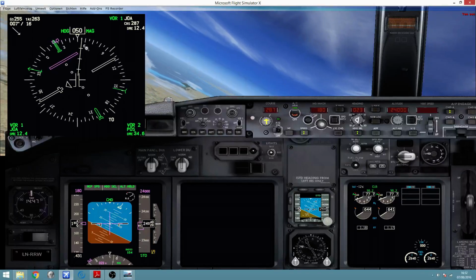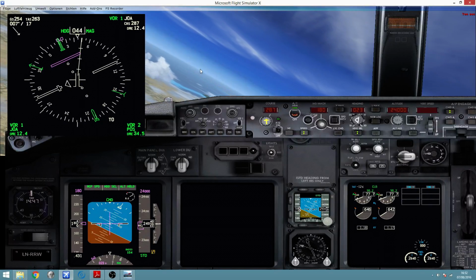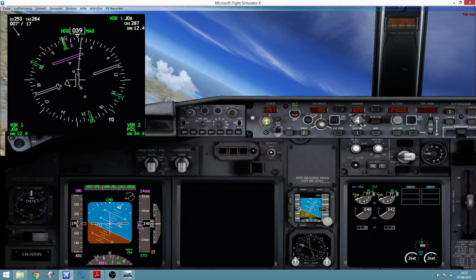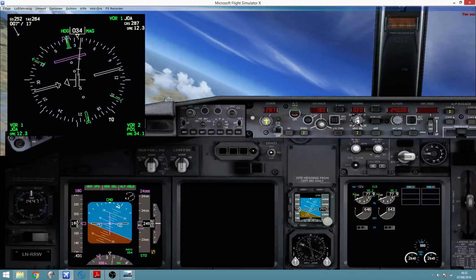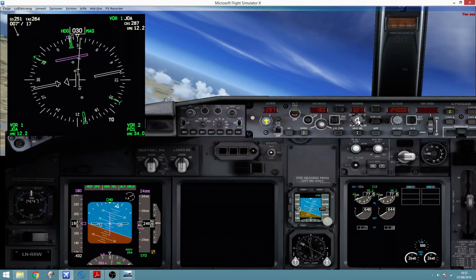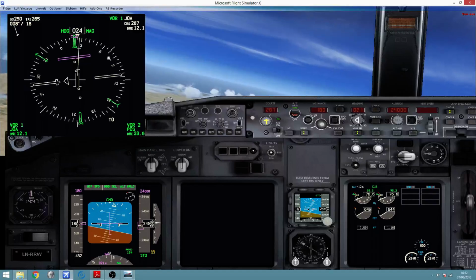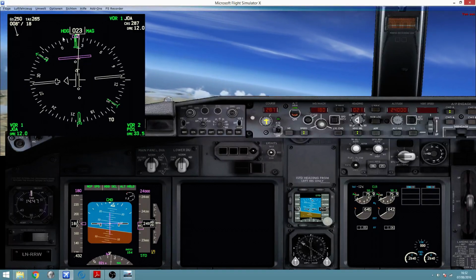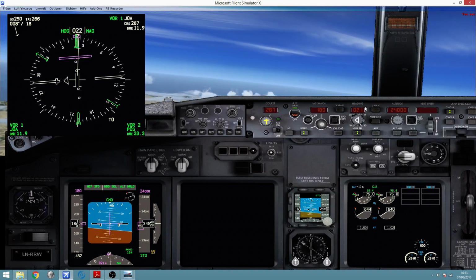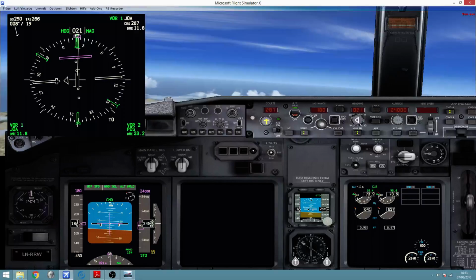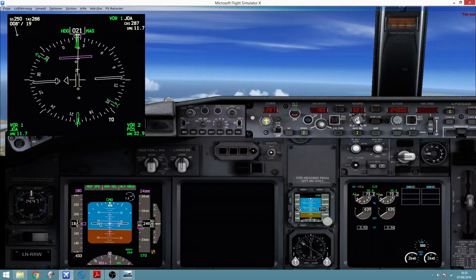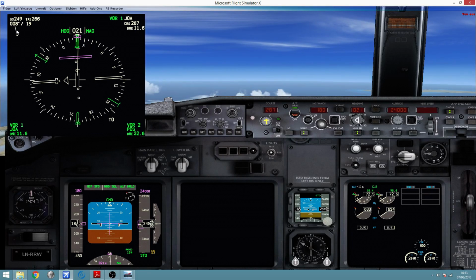So here on the navigation display, let's finish the turn. Good. So I make it coincident. Let's say 021 seems to be fine. All right, so the aircraft is currently flying with a magnetic heading, which is this indication that we have here, heading magnetic of 021, which is the one that I told the aircraft to fly at. What's going to happen, since the wind is slightly coming from the left, the aircraft is going to drift to the east of our position.